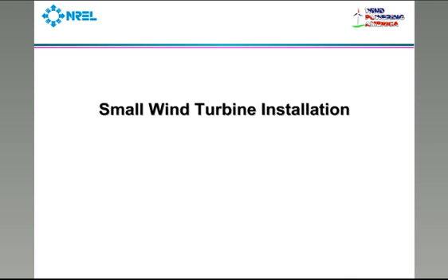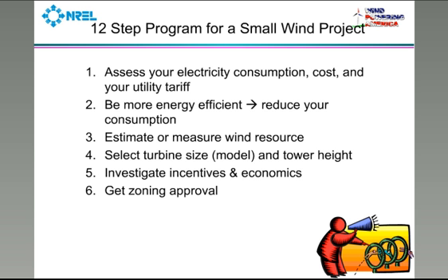Installation. This is I think the last big topic I'm going to cover. I offer you a 12-step program for installing small wind projects. Just kind of in brief, assess your consumption, your cost, your utility tariff. Before you spend money on the turbine, spend some money making yourself more energy efficient. Money spent on energy efficiency will typically pay off much faster than money spent on either wind or PV.